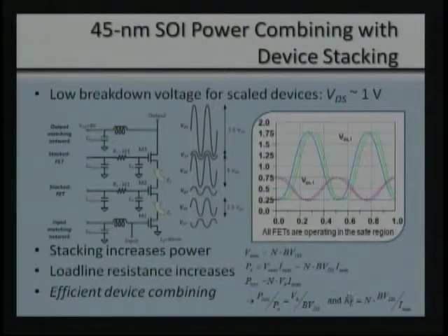We can essentially design our device size to produce a load impedance that's close to 50 ohms at the output of this top device. That limits how complicated the output matching network is and how much loss we have to incur, and has allowed us to achieve some very interesting results.